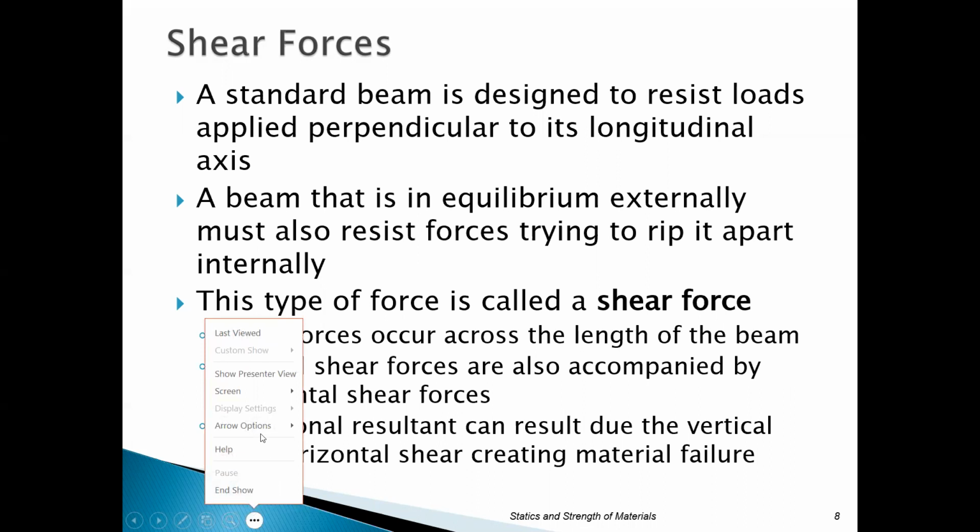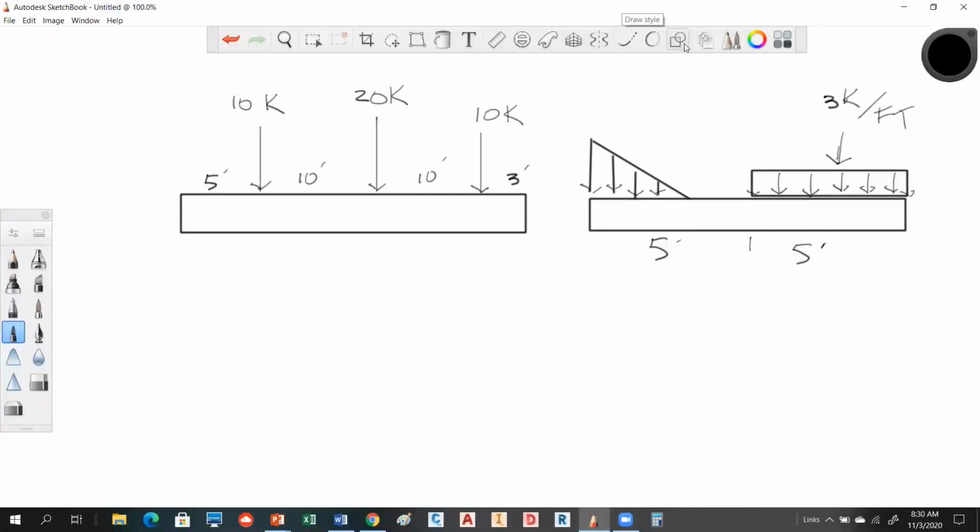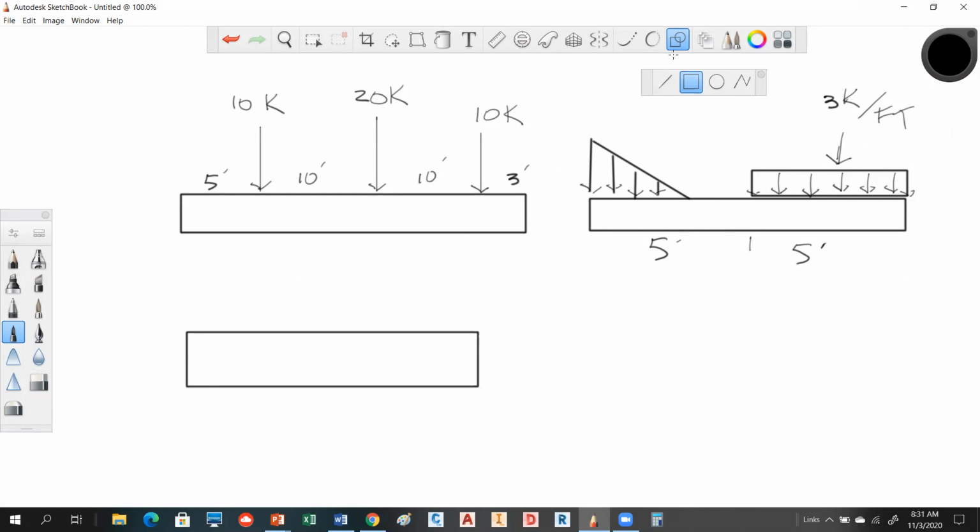So again, if we look at a little simple picture over here, just to kind of show you what's going on here. Let's see my screen. If I go here, what we're looking at is if you have a beam that's in shear, you're going to have shear forces that are going to be developed kind of like here. So this would be a shear force, and shear is usually denoted as V. So this would be a shear force vertically. That's going to be accompanied by a horizontal shear, a shear force horizontal. But what will happen on that increment, you're going to get potentially, well, actually, this would probably be going that way. Let me do that. If I'm looking at the way that's actually acting, it's probably getting a diagonal shear coming like this. And that can be detrimental to concrete and different types of materials. And actually, concrete will start to fail in that direction. You'll actually see stress cracks that can develop either vertically, horizontally, or diagonally, which can really rip that apart.